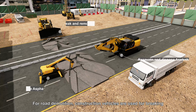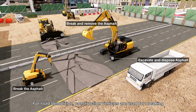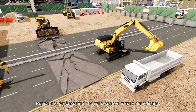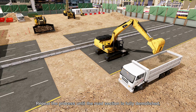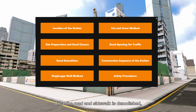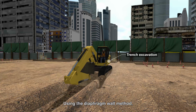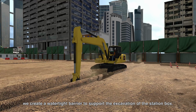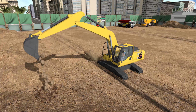For road demolition, construction vehicles are used for breaking the existing asphalt into small pieces and removing them. Repeat the process until the road section is fully demolished, ready for the next construction stage. Once the road and sidewalk is demolished, a diaphragm wall method is performed. Using the diaphragm wall method, we create a watertight barrier to support the excavation of the station box.